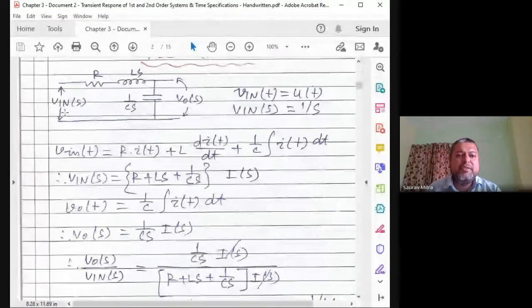So here, if you are giving 1 volt, the output voltage will start from 0 because you are considering an initially relaxed system. So initially the voltage across the capacitor is 0, and the voltage will start building up from 0. Not necessarily, if a capacitor has initially 4 volt or initially minus 3 volt, it will start from that. And the final value of the capacitor voltage will be 20 volt if you are inputting Vin as 20 volt, but after certain time.